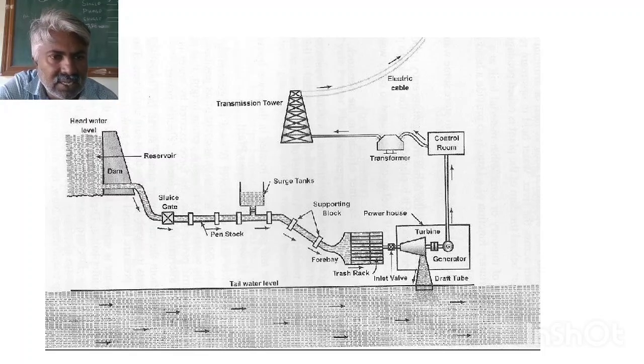What we see here is a dam, that is called a reservoir. So more amount of water that we get during the rainfall season, monsoon season, will be collected and stored in the dam. So when the enormous water is stored, it reaches the fullest capacity. At the bottom of the dam, you will have a pipeline, and it can be controlled by means of a gate valve. So for power production, when the dam is at full capacity, if you want to produce power, you have to open the gate valve.